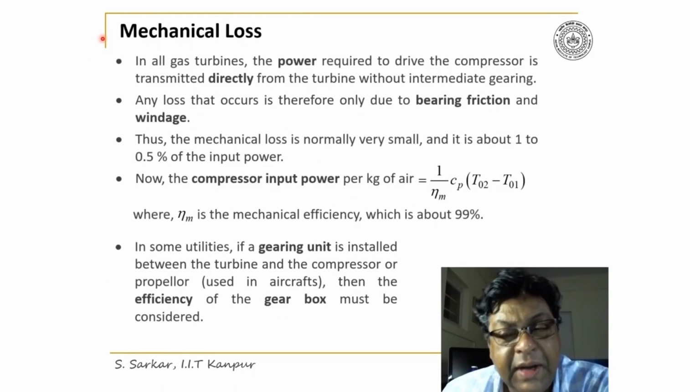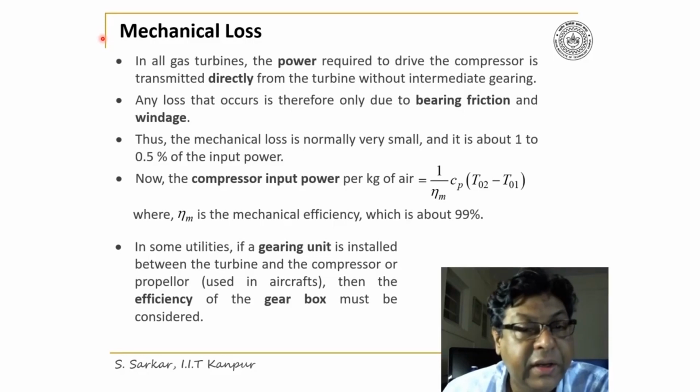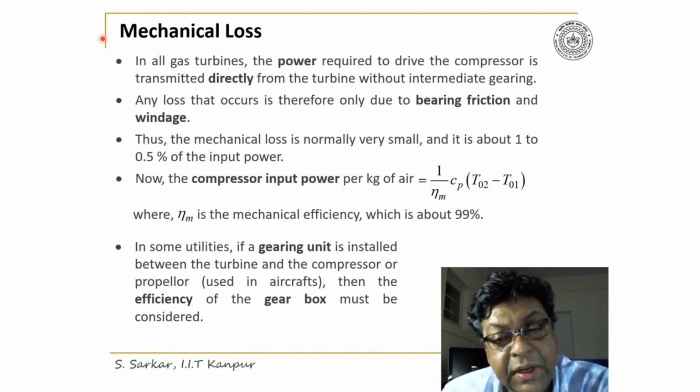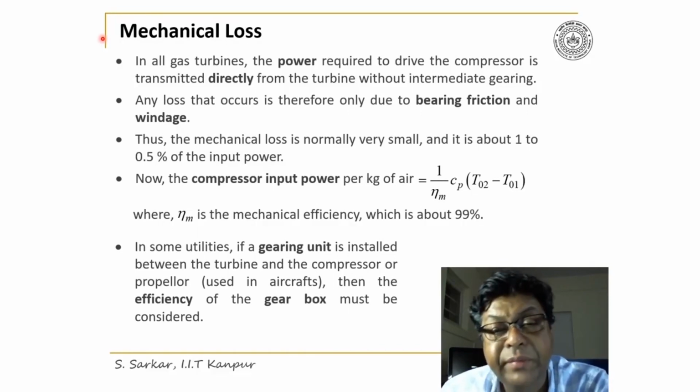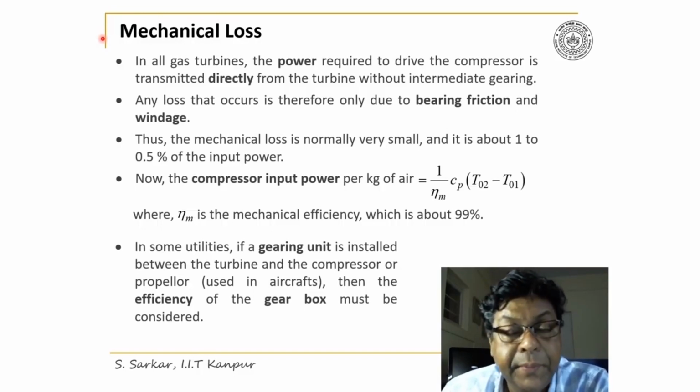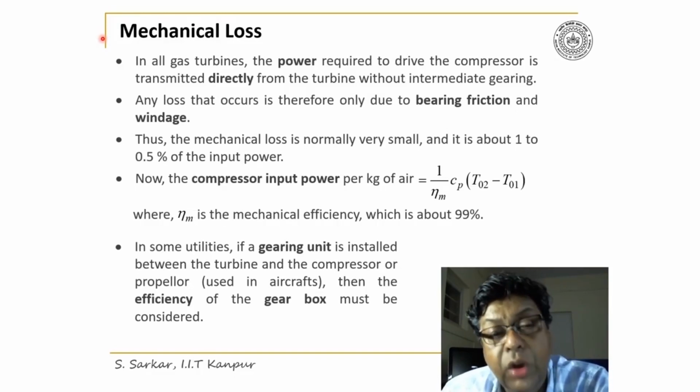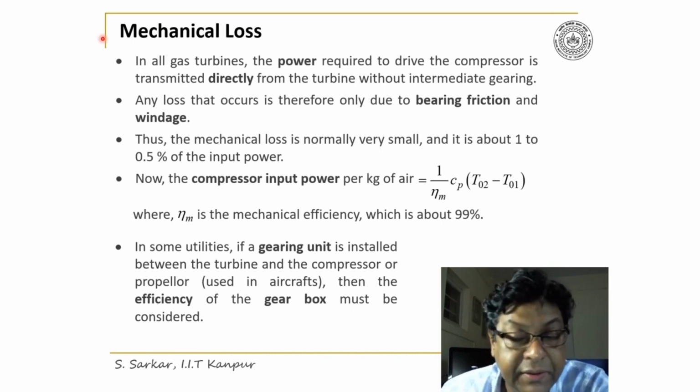I'll discuss now the mechanical loss. Now in all gas turbine units, the power required to drive the compressor is transmitted directly from the turbine without intermediate gearing. Thus, any loss that occurs is only due to bearing friction and windage.